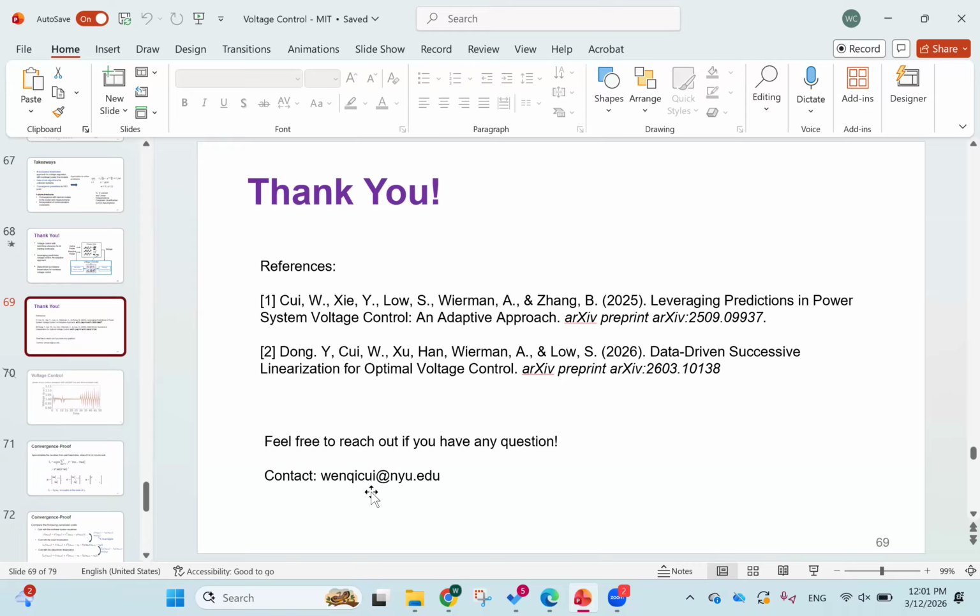Even successive linearization won't work. I may need some very clever feedback linearizing control or sliding mode control that is actually going to work under those big jumps. So there are a lot of assumptions here, and even some state of the art doesn't work because of those assumptions. Which assumptions are we relaxing here to solve something that we otherwise don't know how to solve? That would help a lot.